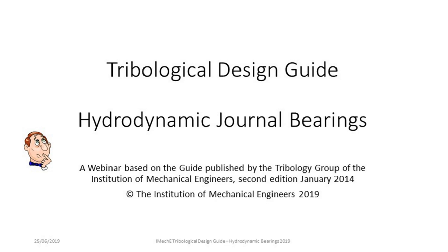Okay, well, the way I think of a spiral groove bearing is really a bit like a Rayleigh step bearing. I mean, the load carrying support, and we haven't talked about Rayleigh step bearings at all, but it's more like a thrust bearing. Actually, the actual mechanism that generates the lift in a spiral groove bearing.